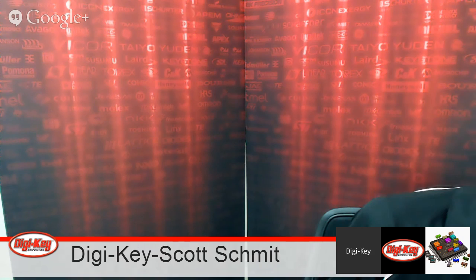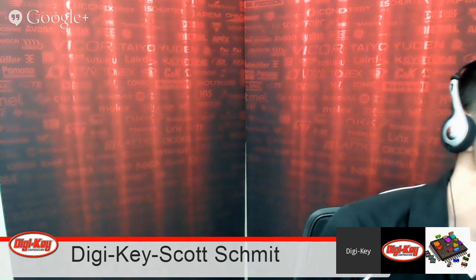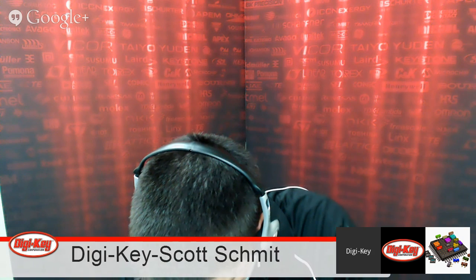Now the next question you may ask is, how do I go create these UARTs on the UDBs? Well, Cypress already does that for you in terms of components. The component catalog that you saw on the right side of your tool, we release new components every 8 weeks, and we offer them as free downloads. The UART built on the UDB is one of those components that's available in your catalog, so all you have to do is drag and drop and use that 3rd or the 4th UART in your design.